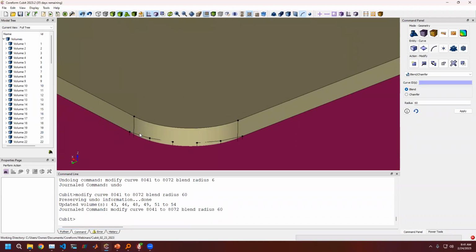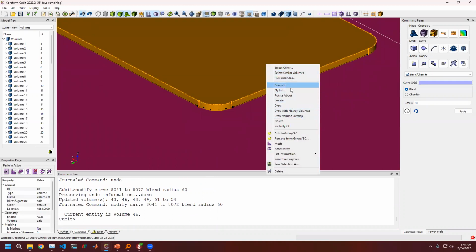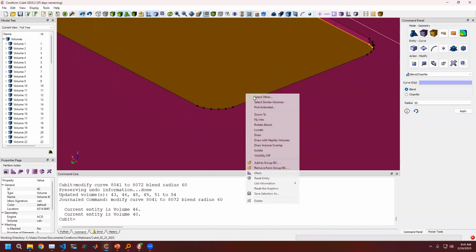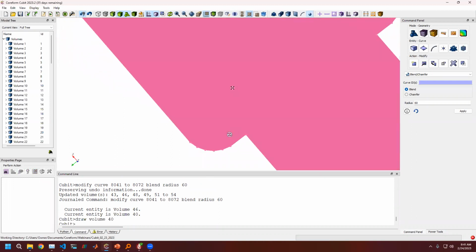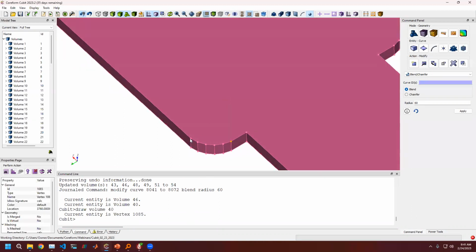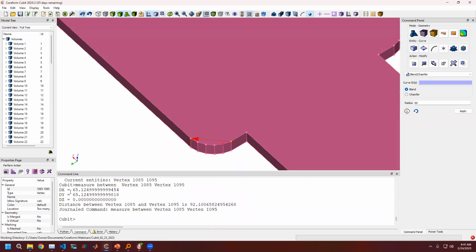So there's some like 62.5, but that's just an option where it's now in actual CAD. Just to show how I might have measured to get what that entity might have been, if I draw this other surface here, this is essentially a circle. If I click two vertices, right click and measure, it's going to give me the components of those distances. Because these happen to be aligned with the X and Y plane, I can see that 65.125 would be the radius that would turn that blend into.